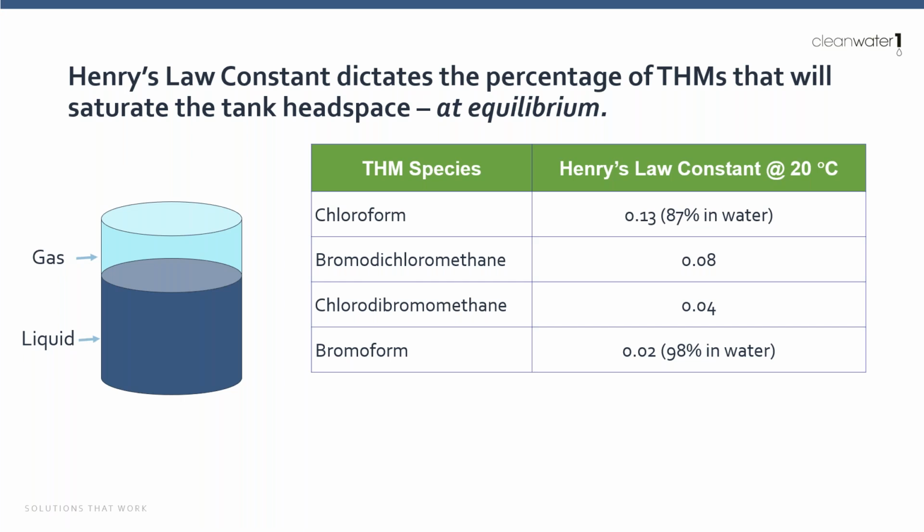But it's really important to note we can strip all of these, and just that small gas phase concentration for bromoform is still sufficient for us to implement treatment. We just need to understand what the speciation of your trihalomethanes is so that we can plan accordingly. It's really mostly about how much air we move. The more brominated species require additional airflow.